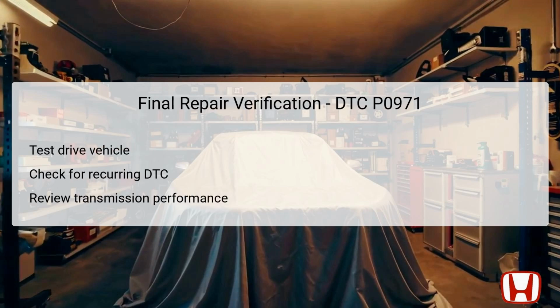After completing the necessary repairs and replacements for DTC P0971, conduct a final verification to ensure that the issue has been resolved effectively. Start by taking the vehicle for a test drive to observe its performance under normal driving conditions. Monitor for any signs of erratic shifting behavior or limitations in gear selection. Following this drive, utilize the HDS again to check for the reappearance of DTC P0971 or any new codes that